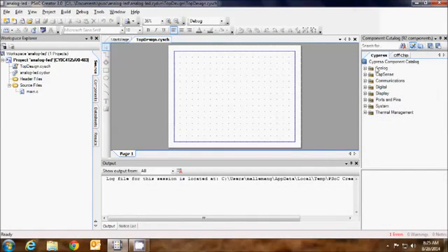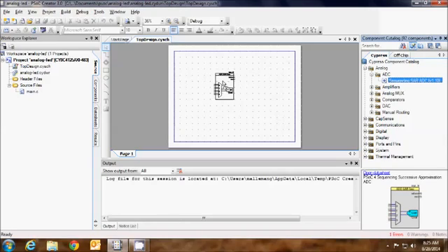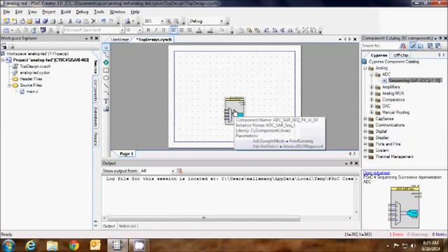So I guess the first thing we'll do is grab our analog to digital converter. Now it's a multi-channel converter. By default you can see there are 4 channels, all differential inputs. So I'm going to change that to a single channel, single-ended.